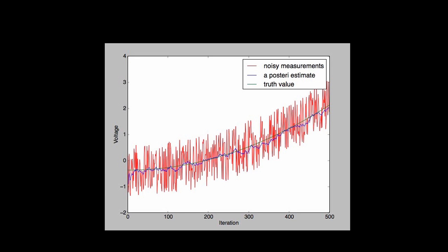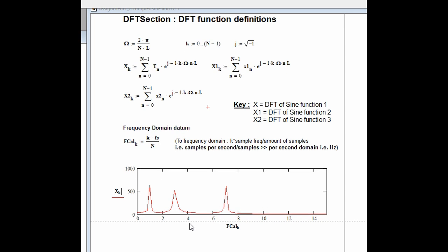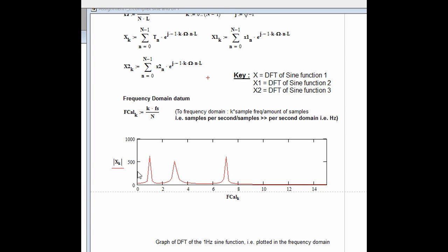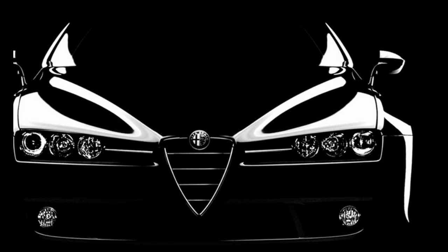So this is typically where a Bode plot comes in, the name Bode plot. A filter's Bode plot shows where it's supposed to act in your frequency domain. If you want a low pass filter, and you've seen this before, there's a line and it goes down there and takes off. So the Bode plot means everything under that line must go through, and as it goes down, everything else must be made softer or taken away, so that you're only left with the frequency you're really interested in. So back to sound processing.